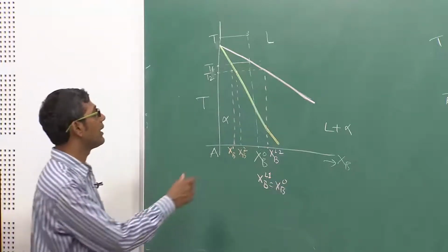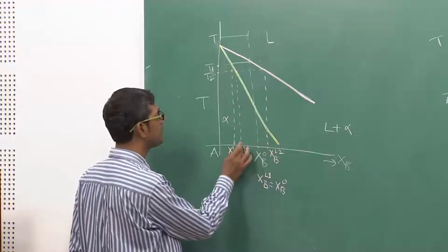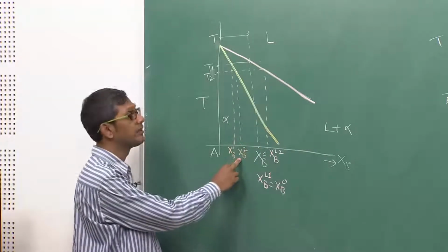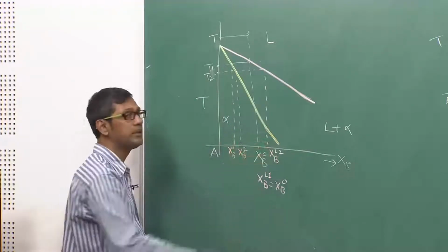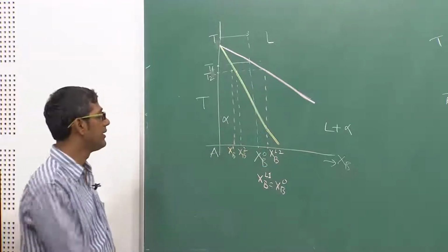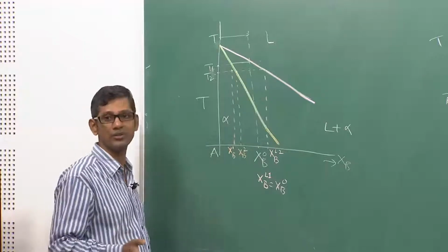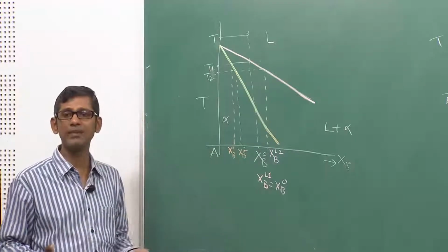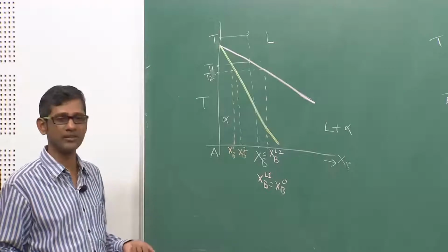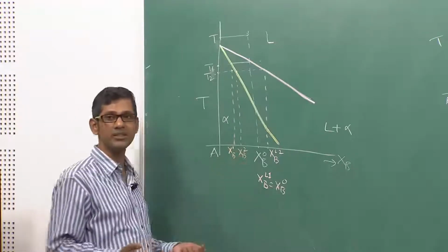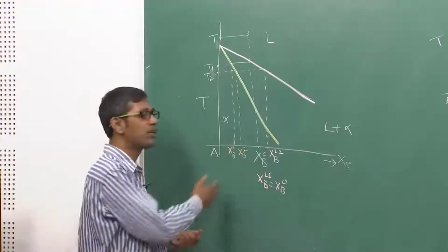So again I have a difference between the solid which is formed at the temperature T2 and the liquid which is present in contact with it, and this difference is the solute rejected into the liquid, because you cannot create mass, you cannot destroy mass. Whatever is present in the system must be balanced between the solid and liquid.